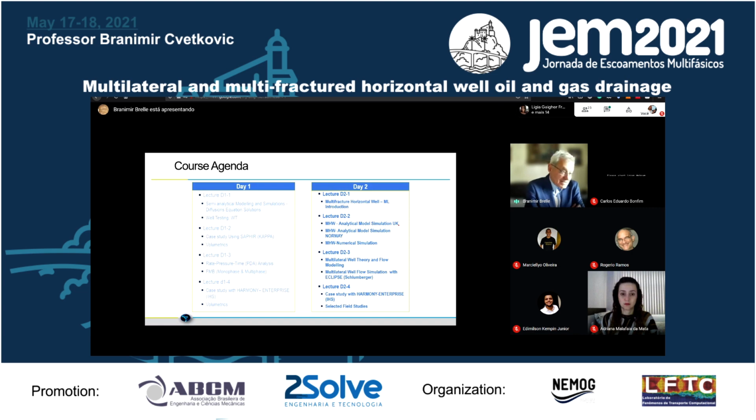And as well testing is also an analytical model, immediately you can say that this model is derived from the diffusion equation. We yesterday talked about the diffusion equation. Otherwise, a reservoir simulation model is more capable, maybe in catching very many physical properties from the reservoir and modeling them, because it is solving non-linearity by introducing a numerical method, finite differences, not finite element.